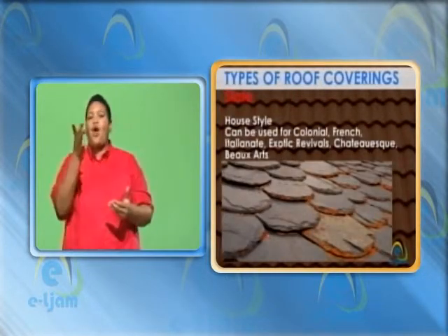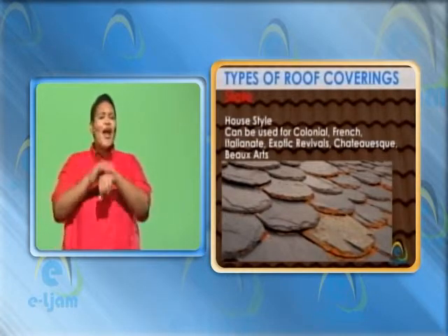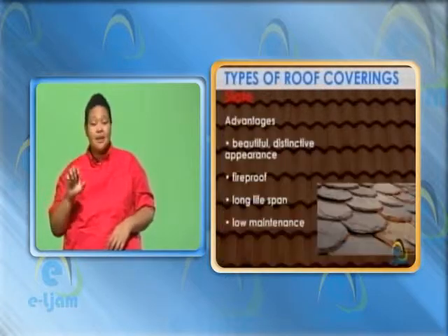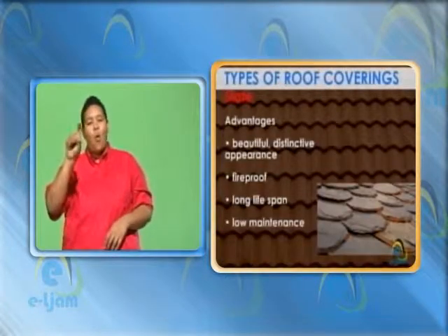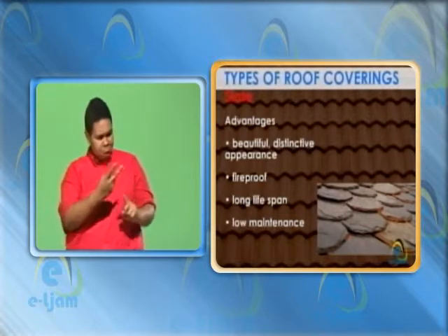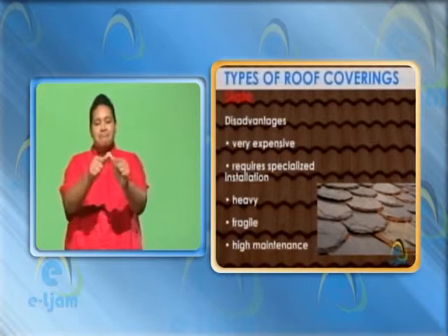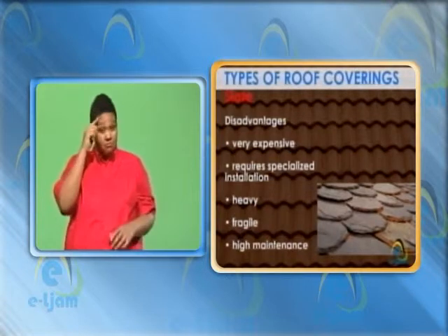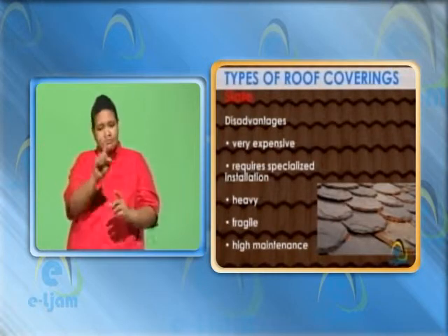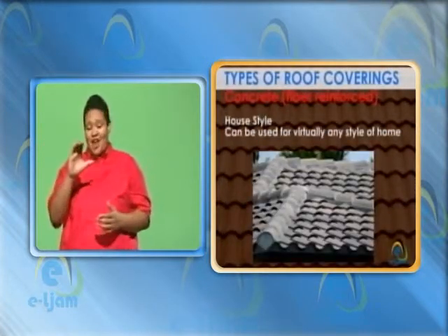Slate. House style: can be used for colonial, French, exotic revivals, chateauesque, Les Beaux-Arts. Advantages: beautiful, distinctive appearance, fireproof, long lifespan, low maintenance. Disadvantages: very expensive, requires specialized installation, heavy, fragile, high maintenance.